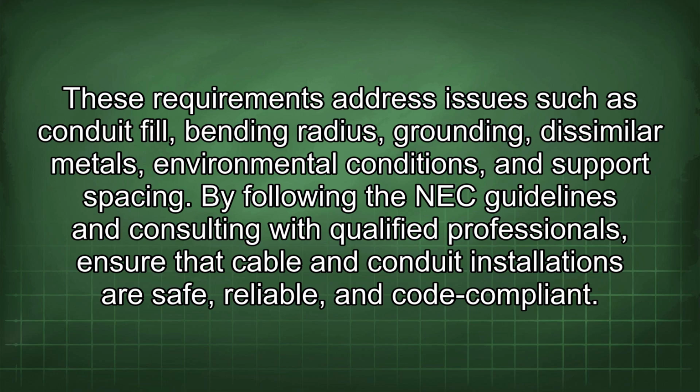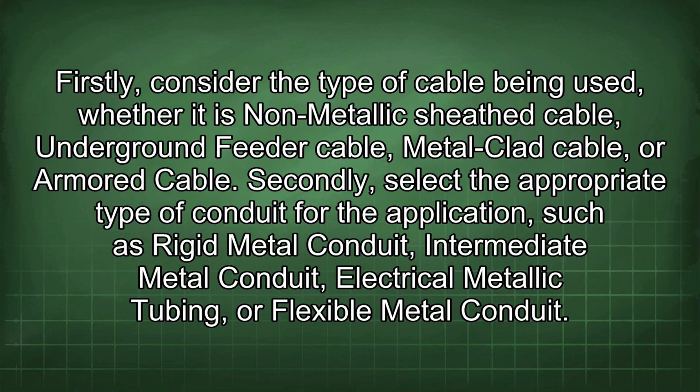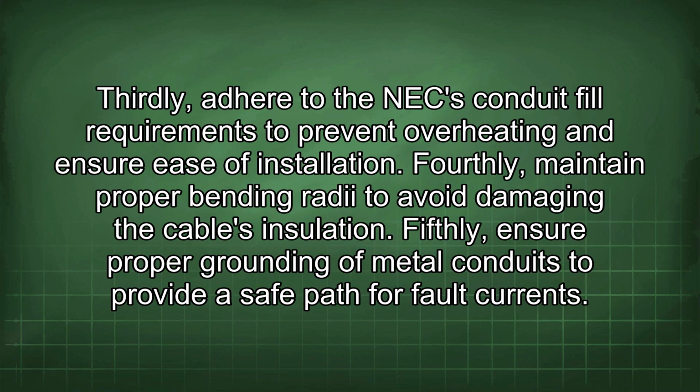code compliant. Firstly, consider the type of cable being used, whether it is non-metallic sheath cable, underground feeder cable, metal-clad cable, or armored cable. Secondly, select the appropriate type of conduit for the application, such as rigid metal conduit, intermediate metal conduit, electrical metallic tubing, or flexible metal conduit. Thirdly, adhere to the NEC conduit fill requirements to prevent overheating and ensure ease of installation. Fourthly, maintain proper bending radii to avoid damaging the cable's insulation.